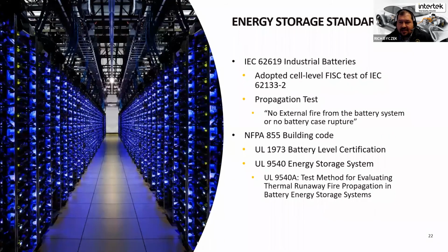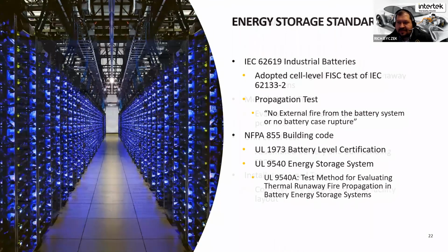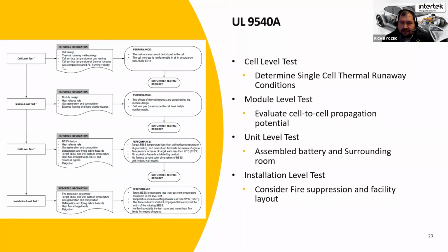Energy storage, again, a lot of the concern here in North America within the UL 9540 standard, which is for the energy storage system, batteries, inverters, et cetera, enclosure. We have the UL 9540A test method, which has a very prescriptive process for evaluating thermal runaway from the cell all the way through the full installation and considering the fire suppression in the vehicle or the room in construction around it. I mentioned a prescriptive process here. We start with a cell level test. We go through a module level test, then a unit level test, an installation level test with essentially gateways along the way.